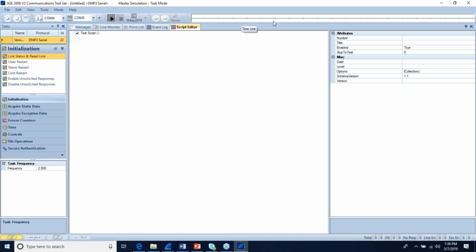And then up on the upper right-hand side, this is our timeline, which is used for real-time display of communication signals. Like the BCOM unit, this is a device troubleshooting aid or an application troubleshooting aid. You'll see live traffic here shortly. It simply will tell you when you see a carrier signal detected and an RTU response. It's a fairly good indicator of when you're trying to identify setup discrepancies or understand why a device is either not responding or you're getting some sort of error result.